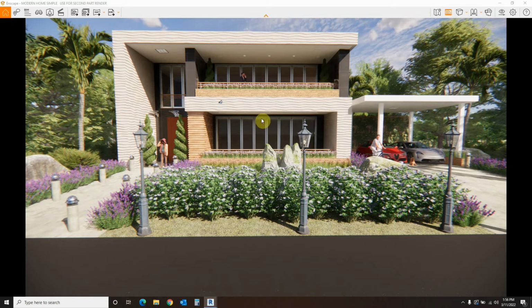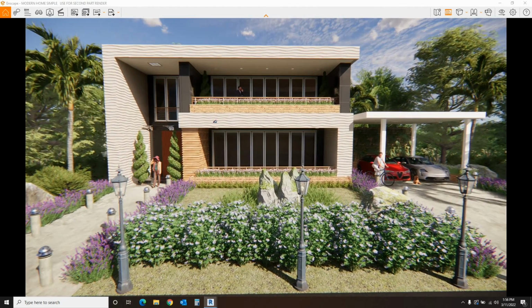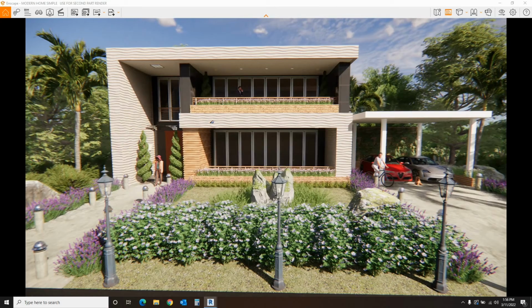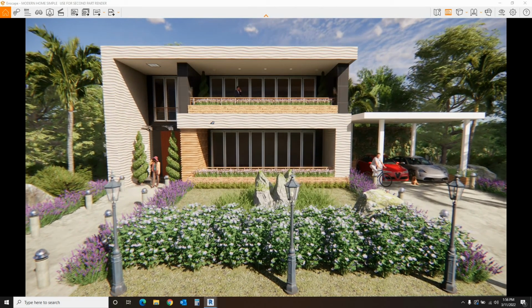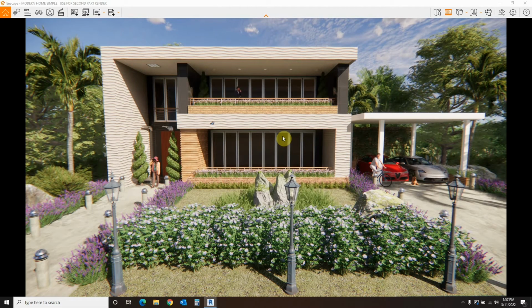And I also notice that it's a little high. I can actually change the placement of my camera by bringing it down a little bit this way. Okay, and maybe coming in a little closer like that. Maybe rotating it, using the buttons on the mouse to navigate, very much the same way that you would do in items such as Revit, by just going ahead and using right button, left button, and wheel mouse. Great, this is looking very nice with the position of the camera. Excellent. Then let's have a look at some of the other controls that we have here.